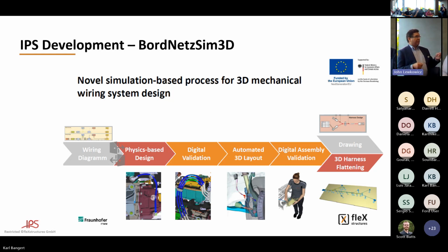So that includes going from this design into a variety of different usable models, in this case IPS models, to do cable simulation, installation studies, have a connection to a database, which in itself is going to be the component piece that we'll be talking about a bit more in the future, called FlexHub, an interface to your database so that we can get different wire types, different connector types, clip libraries, and have that all in one central place so it's available to you to work with.